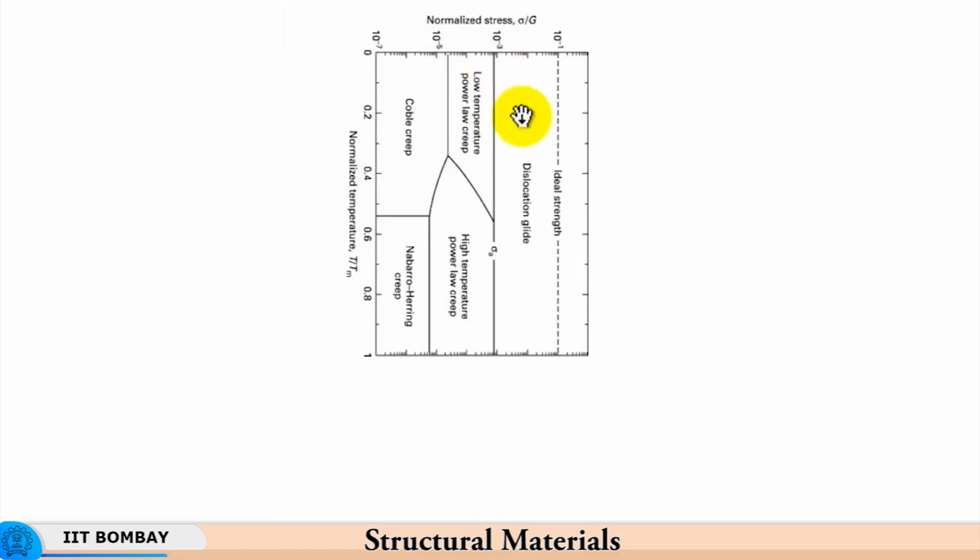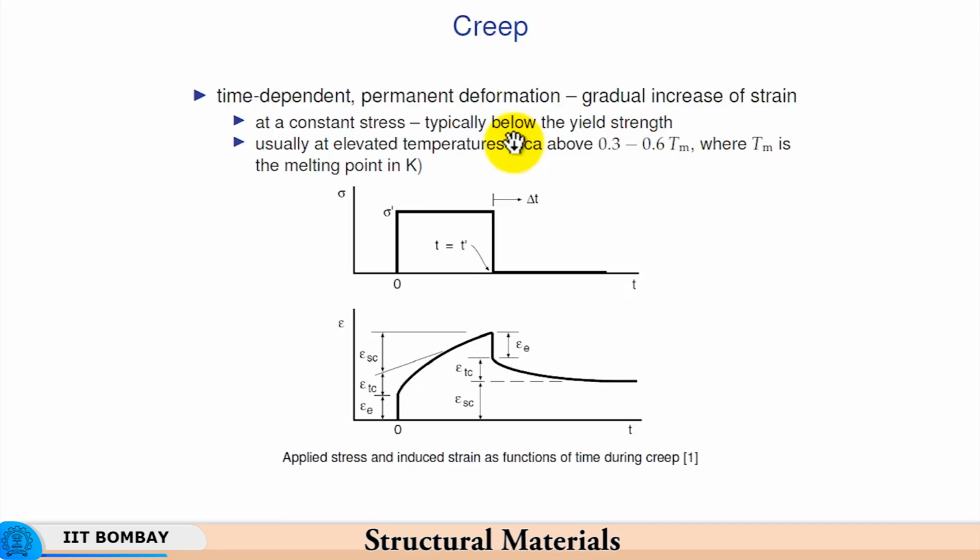And then you have what is called dislocation glide at much higher stresses. So, you see that the material softens, and therefore, even before the normal yield strength has been reached, creep deformation starts. That is because of diffusion taking place. So, at very low stresses, the diffusion in creep starts. Well, if your temperature is relatively low, and you have increased the loading, then you approach a situation of dislocation glide or dislocation mechanisms coming into play. Let us see the creep mechanisms.